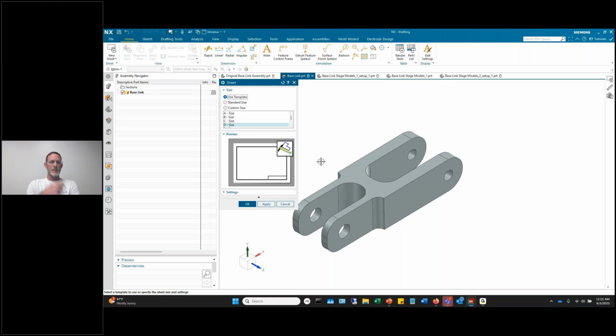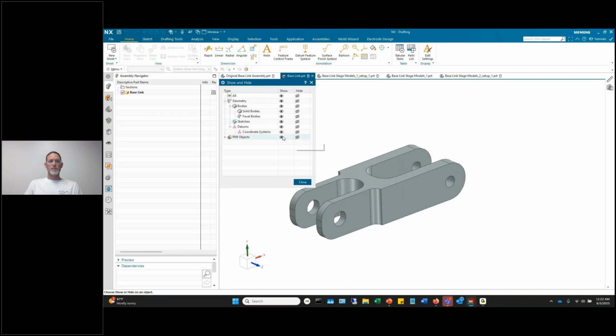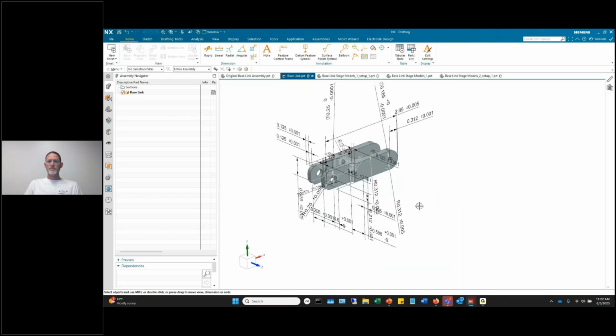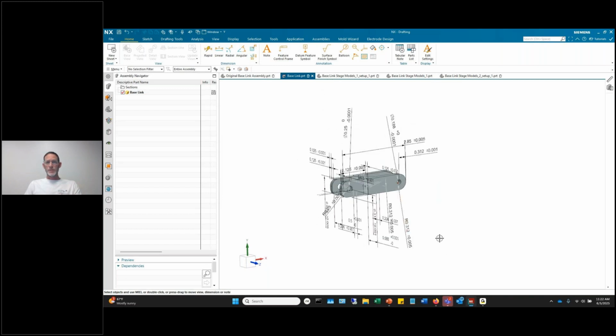Nothing more than a piece of paper that a person can look at and say, at the part, is this right? Is it beneficial? Sure. Is a piece of paper beneficial? No. But is digital? Yes, but to a small extent, just for you to visually check. The better methodology is to utilize PMI data. What is PMI data? Product manufacturing information. You're going to do exactly the same thing as you were going to do on the print. You can put all your GD&T, anything you want right here that is relative to the part. It's fully associative. You change the model, the dimensions change.